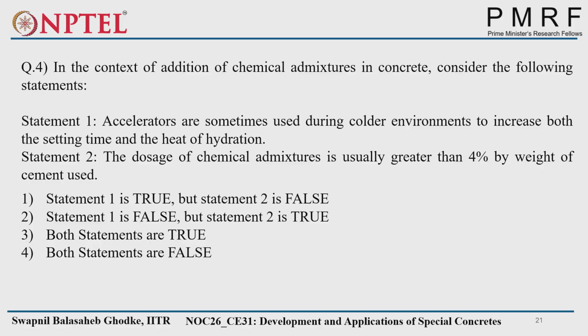Next: Statement 1, accelerators are sometimes used in colder environments to increase both the setting time and the heat of hydration. Statement 2 says the dosage of chemical admixtures is usually greater than 4% by weight of cement. Which is the correct one? One is true, second is false. Any other?